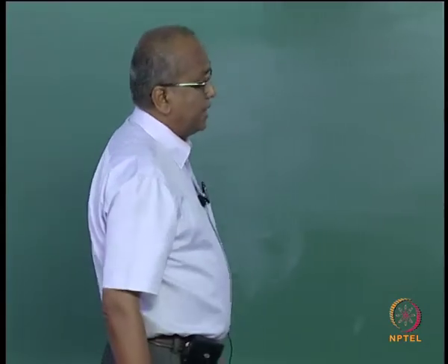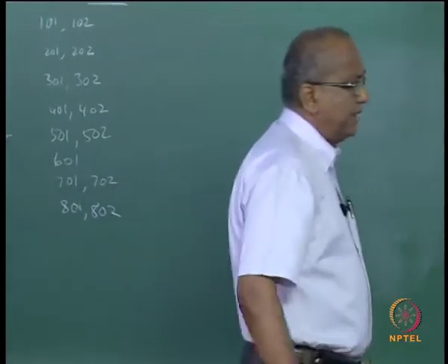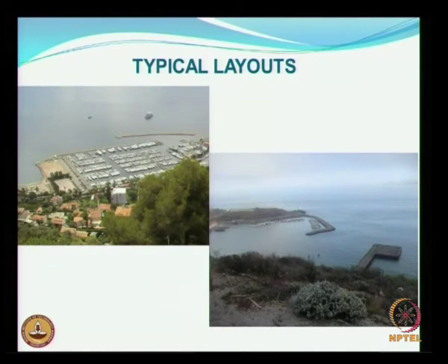So other typical layouts are looking like this, as you can see here. For example, here, although this itself is offering a certain degree of tranquility, if you need more tranquility, then they have extended the breakwater like this, so that the tranquility in this portion increases.